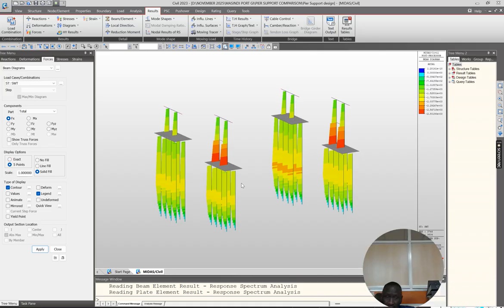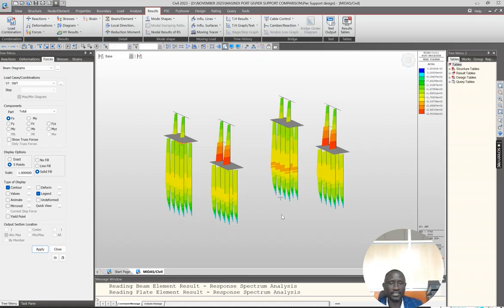Because this pile, you also need to take note that there are two things I learned handling pile. One, pile foundation: you need to know whether it is a rigid pile or a flexible pile or cylinder. So for cylinder pile or flexible pile, normally you use friction, while rigid is when you can use end bearing. But especially for cylinder, you can combine both friction and end bearing. So we modeled it, and we didn't put any support here for the end, so that we simulate this. And that is why when you look at the shear force,